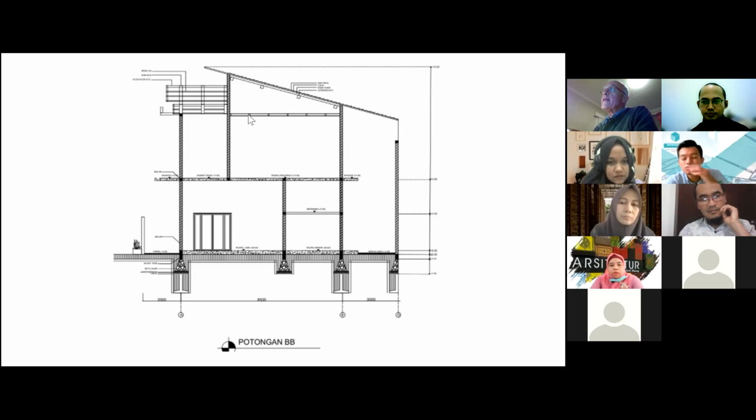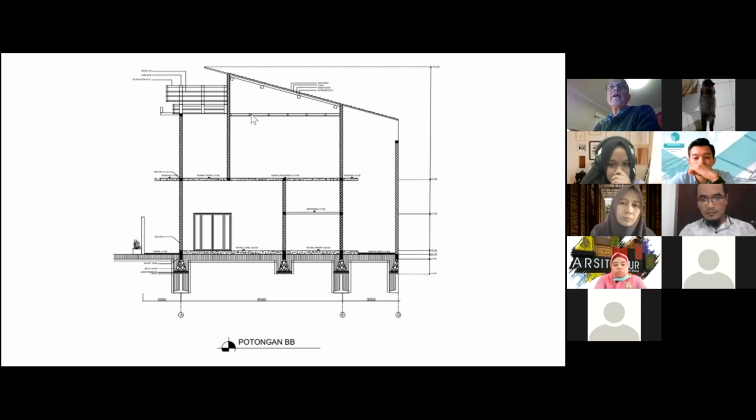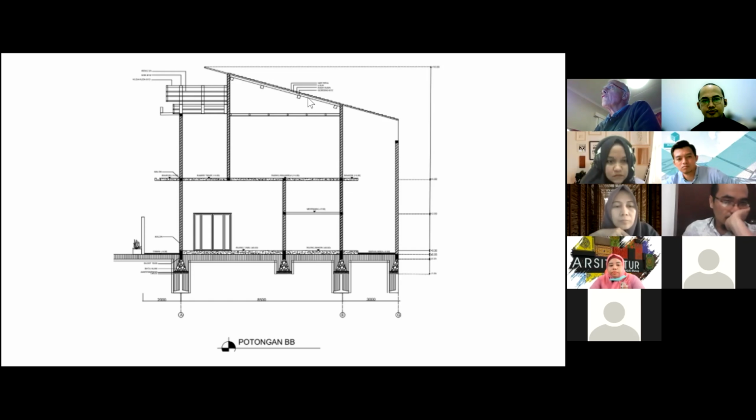Now at the moment, this ceiling is spanning 5 meters and the ceiling joists are only 10 centimeters to span 5 meters. Well, that's impossible. They need to be about 40 centimeters, or say 30 centimeters, to span 5 meters to support the ceiling. And so I think a really good solution would have been to have trusses here to support the gravity loads from the weight of the roofing, the tiles, and the supporting structure. So that's all I want to say about the roof structure.